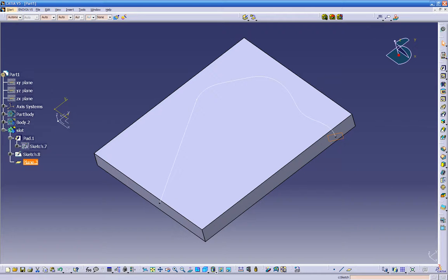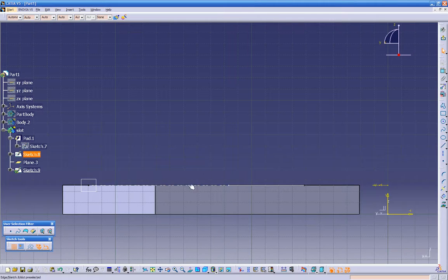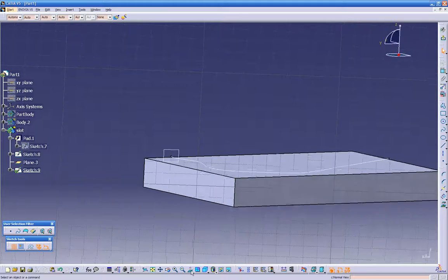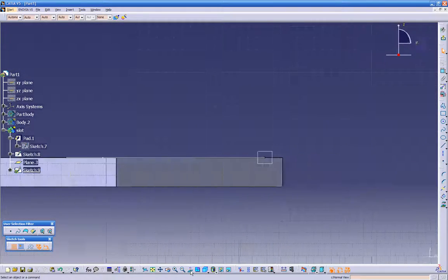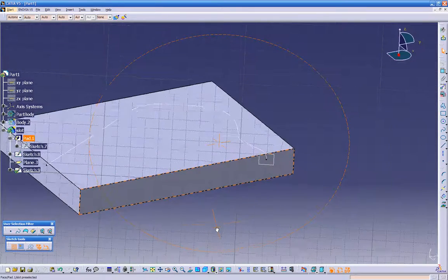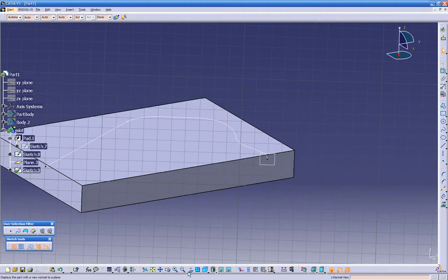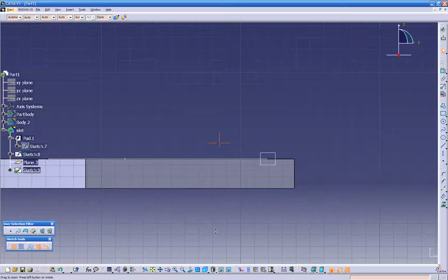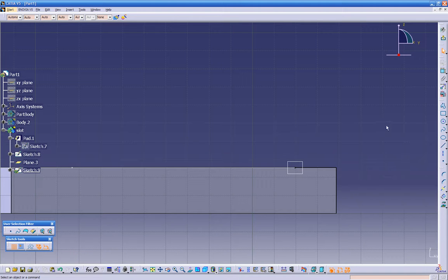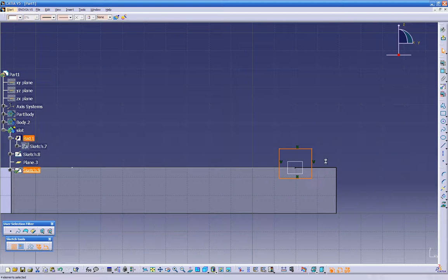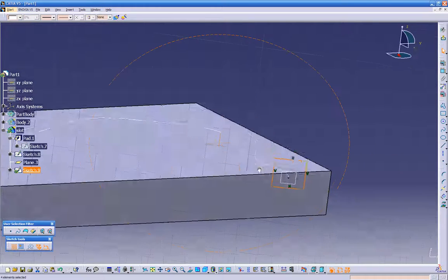Now click on the plane, and let's open a sketch again. So see right now the part is upside down, but we can click normal view 2 times and automatically we are on the front of the part. So normal to the view, we can create ourselves a profile.